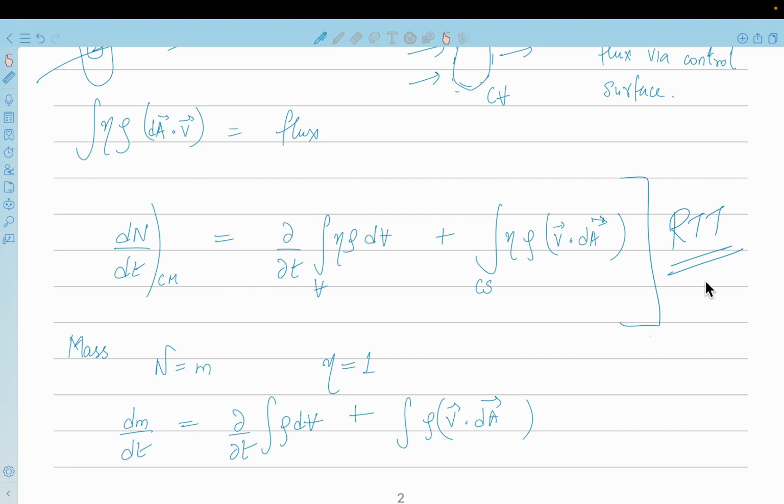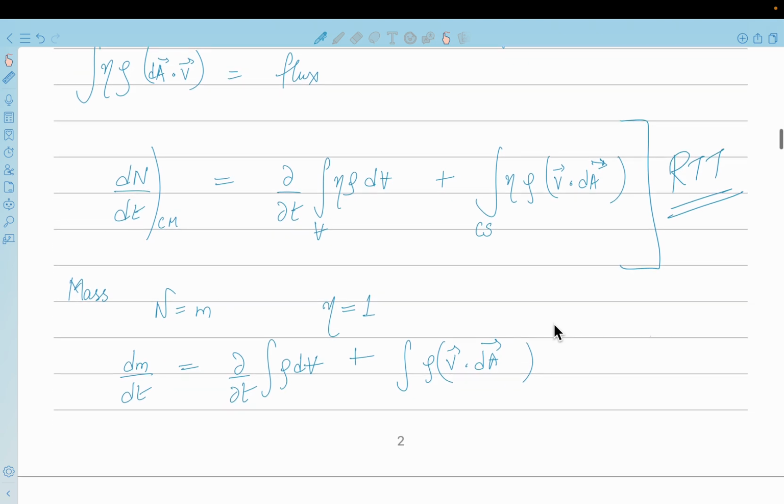That will come from the physical conditions. What are the forces, the viscous forces, external forces, pressure change? All these things will cause change in momentum. Once the change in momentum is caused by external factors, whether we study it from the control mass perspective or the control volume perspective is our choice, and we have a way to relate them, and that is the Reynolds transport theorem. Is that okay?